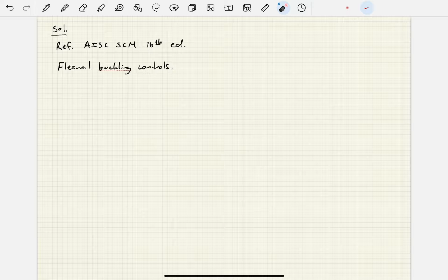So if you remember from your background information on steel column design, flexural buckling could occur with any kind of column cross-section or configuration. Torsional buckling occurs when you have doubly symmetrical cross-sections with thin elements, so the cross-section will tend to twist.